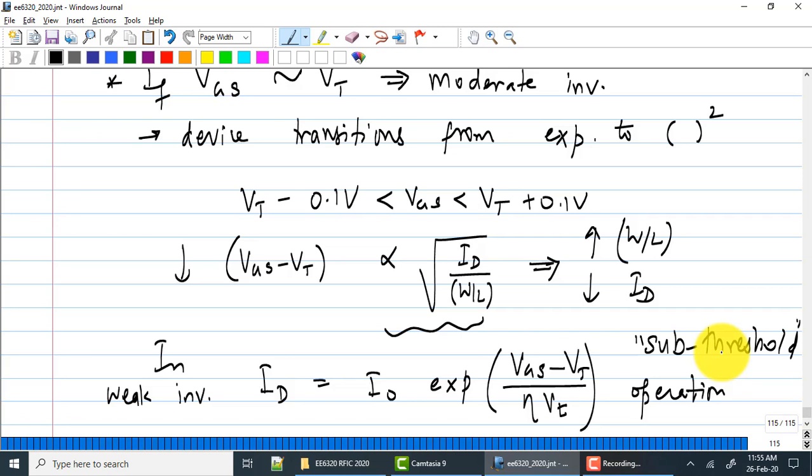This of course will have an impact on your LNA if you decide to operate them sub-threshold. But if you are able to meet the specs, that is perfectly fine, because the LNA is very current efficient in this region. If you are able to meet the gain, noise specs, etc., you will be using very little power, because you have just cut the current consumption by a lot.